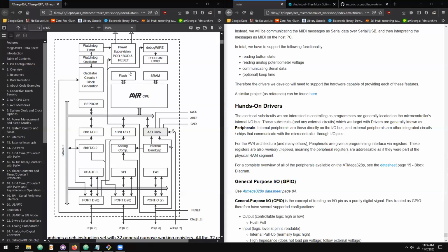But for driver development, it's very helpful to know what you can target and what you'll have to support as an external peripheral. So some device that you plop down on your printed circuit board outside of the microcontroller chip. So peripherals are therefore denoted as either internal, so that's these hardware targets that exist within your microcontroller's integrated circuit, or external peripherals that you have to communicate with via the microcontroller's pins.